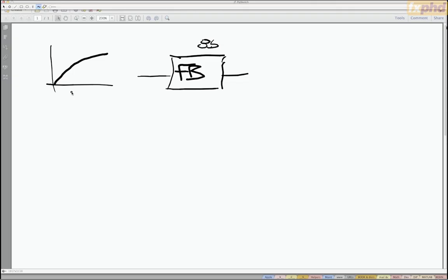So we had scene linear tristimulus, call it T, and we applied a function something like a 0.45 or a 0.5 function to take 18% gray and put it halfway up the scale to be visually halfway. It was left to the display to invert that by using something like a 2.2.